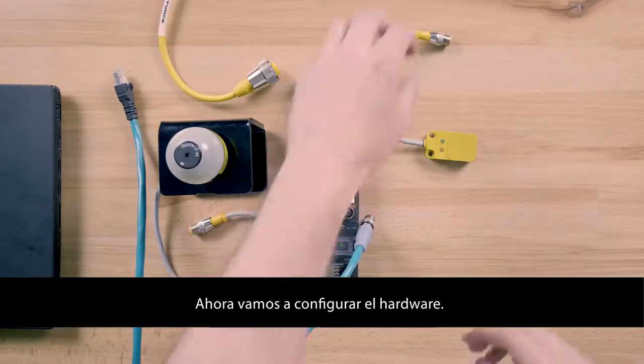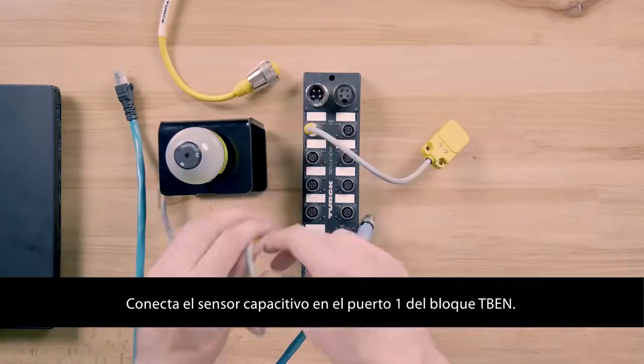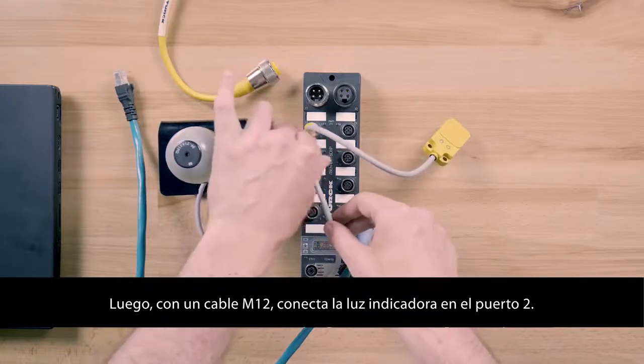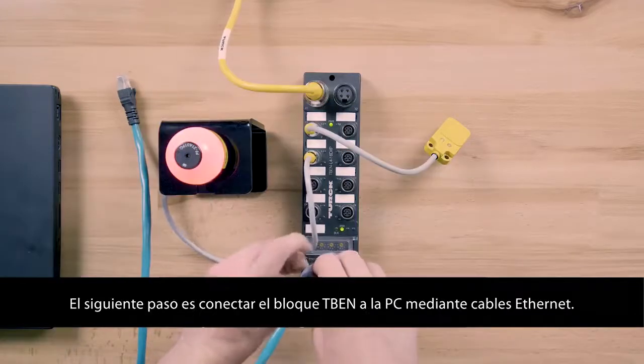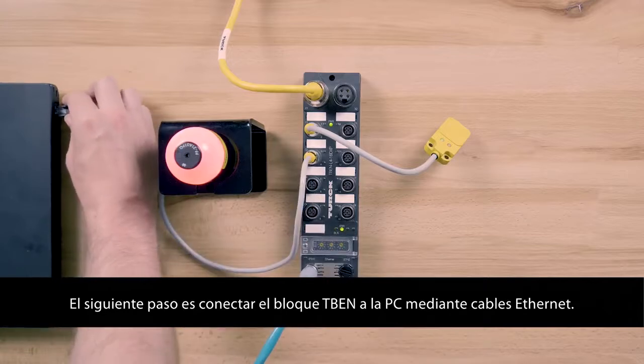Now, let's set up the hardware. Plug the capacitive sensor into port 1 on the TBEN block. Then, with an M12 cord set, plug the indicator light into port 2. Next, connect the TBEN to a 24-volt DC power supply cable. The next step is to connect the TBEN block to your PC using an Ethernet cord set.